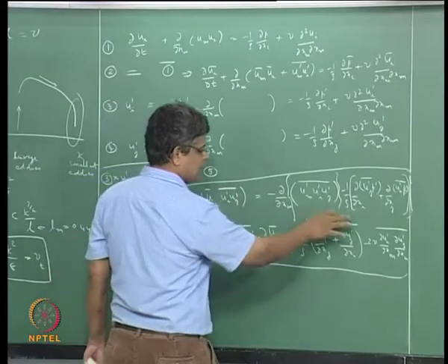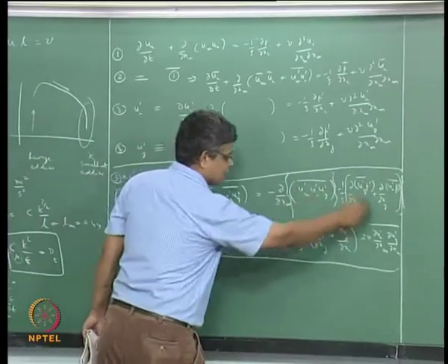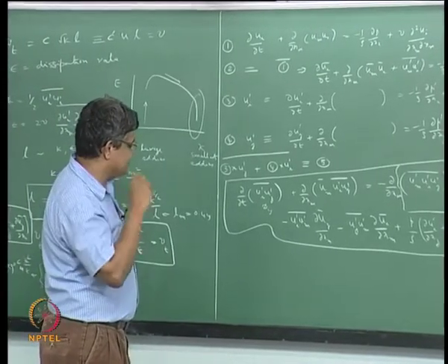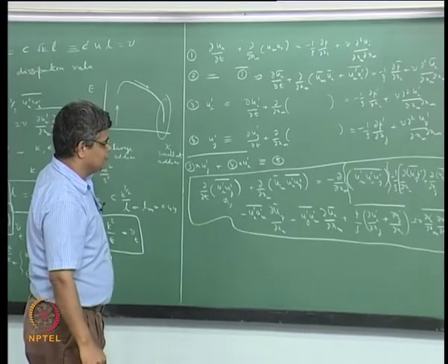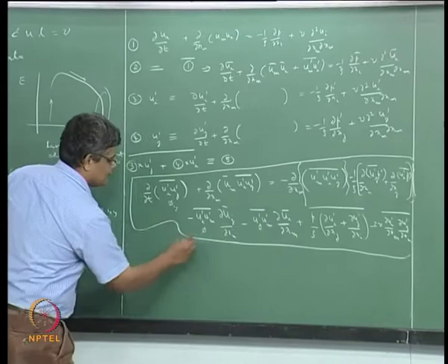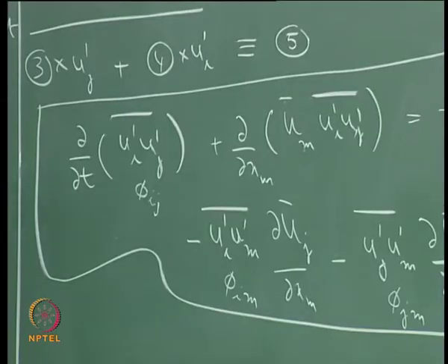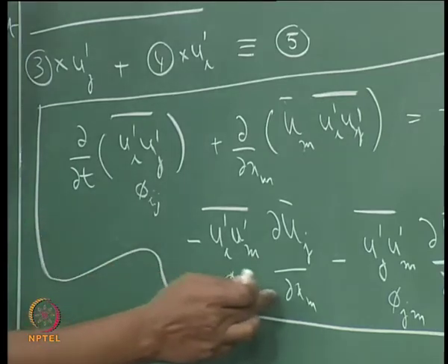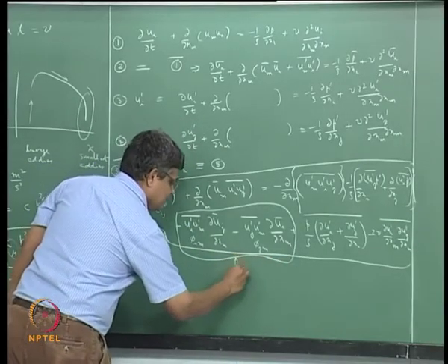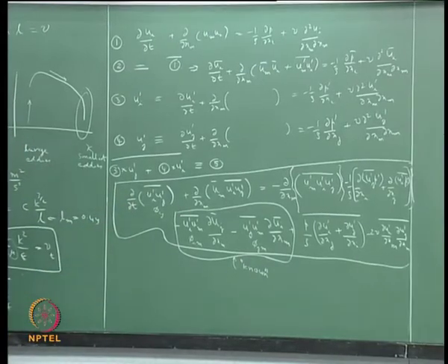We have an advection term and a diffusion term, and then we have a source term here, and so you have all these rest of the terms here which constitute all the unknown kind of things. These are in a way some terms which are known, but these do not fit into the standard diffusion term. For example, here this is another scalar phi i m, and this is another component of this particular scalar. So in that sense one could say that if there are 6 such scalars, these are known terms, and this is also known. So from that point of view, these two terms here are in a way known or knowable when we write all these terms together.